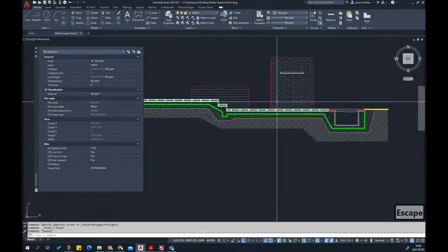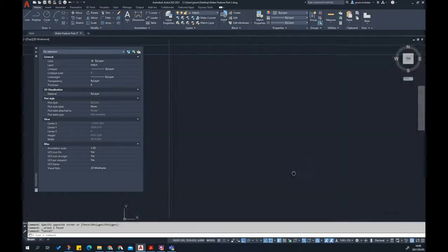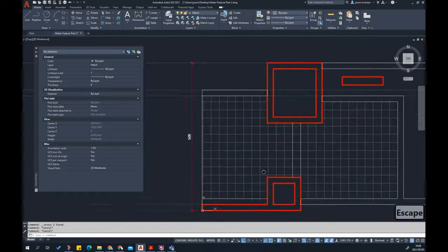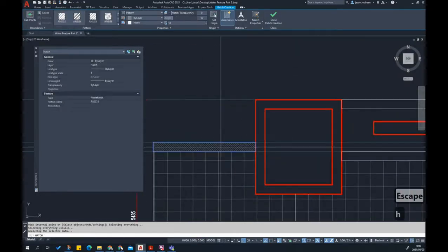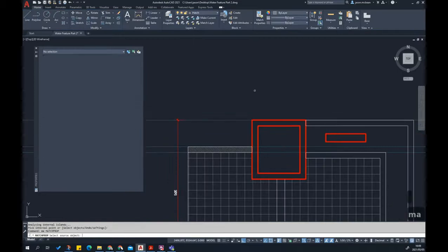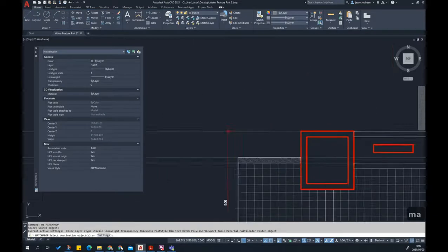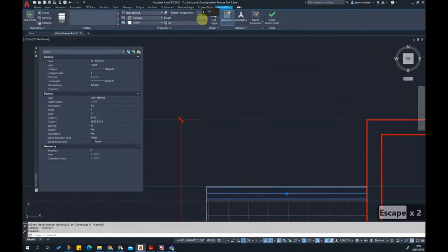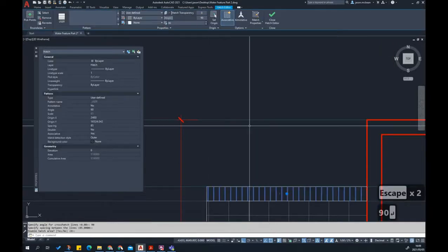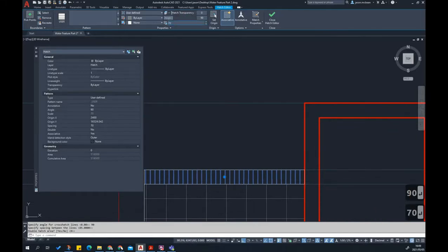Now the next set of hatch I need to create is this coursing, brick coursing for that. So this is 60, so it'll be 70 mil. So I'm going to grab a hatch again. I'm going to say hatch. Again, just select this object over here and then use the match tool. I'm going to match this from here with that. Just remember this will need to be 90. And this one's different because it's 70 mil, because I'm including a 10 mil.